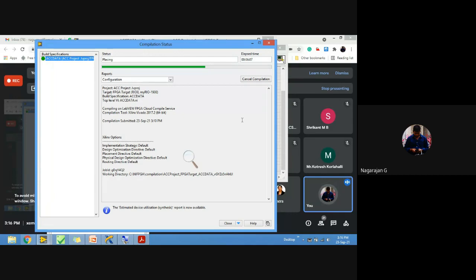Then we have to develop the code in the RT, because only then will we get the bit file and all the references. That's why I have not developed the code in the RT target. We cannot develop the code under RT during this compilation process, because we will not get the references; the first function we will use is to call our bit file. So we have to get the bit file first, and then we'll get all the references properly.